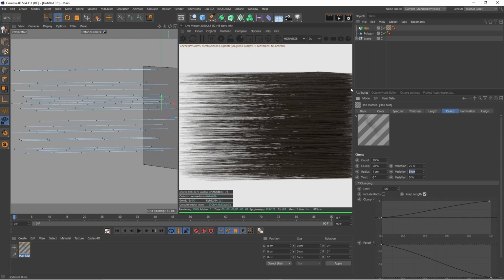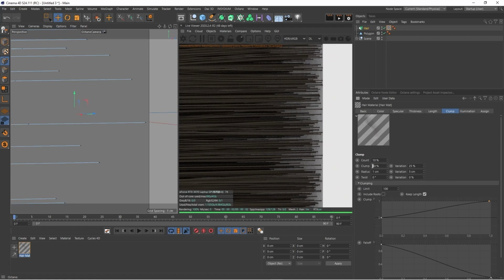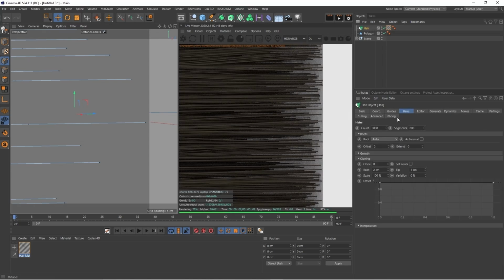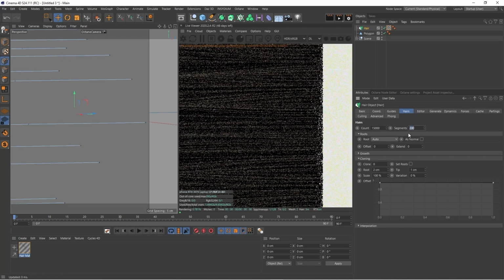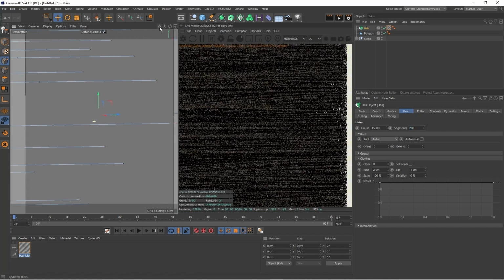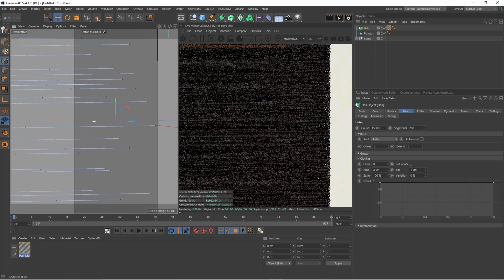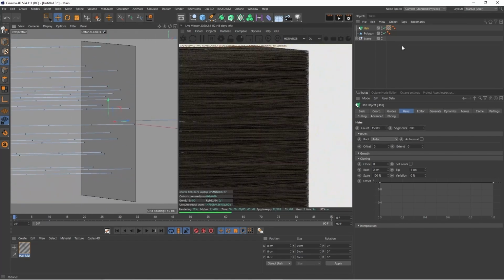Yeah, so if you go to 1 now, it's every single centimeter is the clump. So you've got, let's bring this back up a little bit so we can see the results a little better. And maybe let's increase the hair amount. Let's do 1500. It's going to have to think for a little bit. Okay, so now you can see these clumps. They are 1 centimeter in radius. So in theory, you should have 1,000 of them because it's 100 by 100.